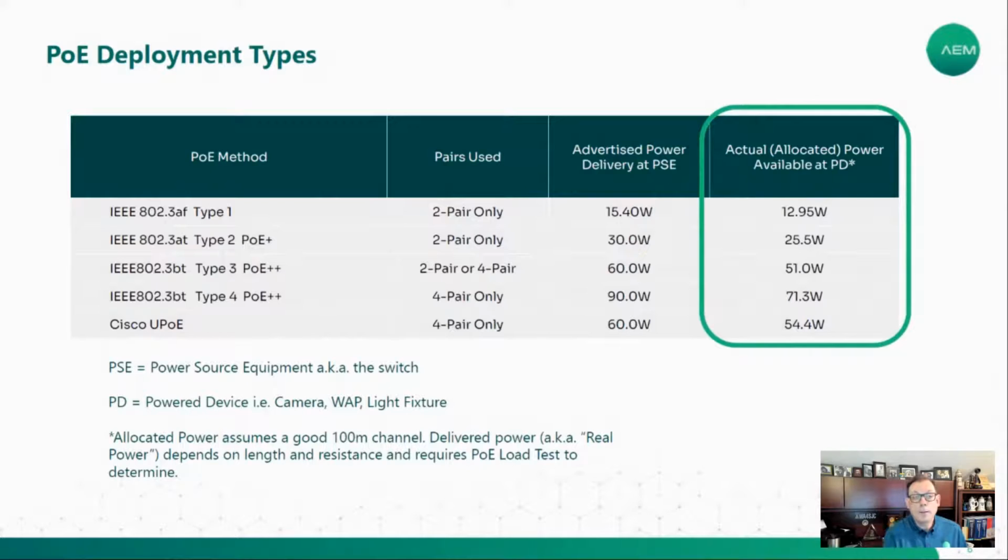And while we're talking about length of cables, I mentioned before that DC resistance troubles can also be caused by patch cords. If you have a really short permanent link, and it looks good, but you have patch cords that are lower quality, cheap cables that maybe you had to pick up quickly because you broke or lost one, and you plug it in, the patch cable becomes a bigger factor on these shorter runs when it comes to DC resistance and DC resistance unbalance.